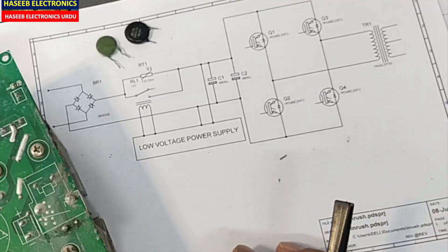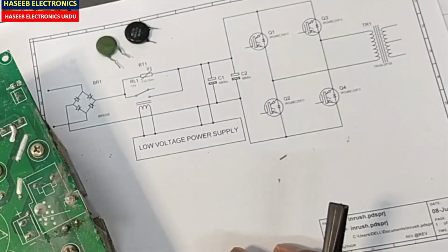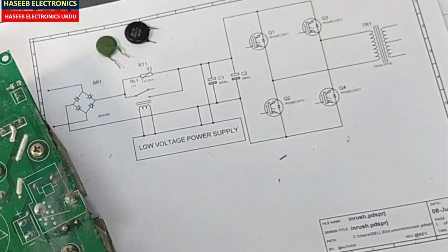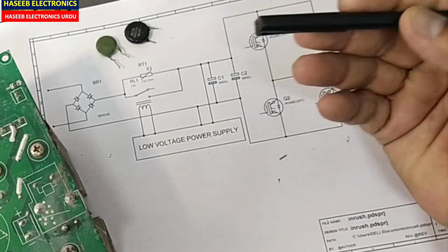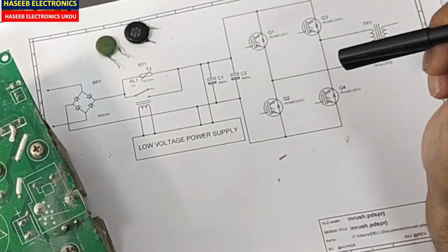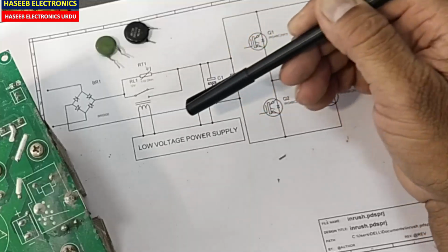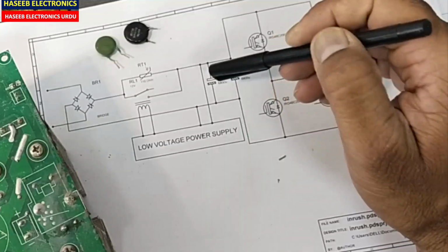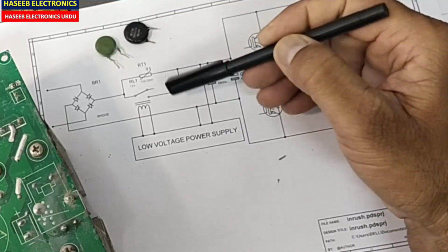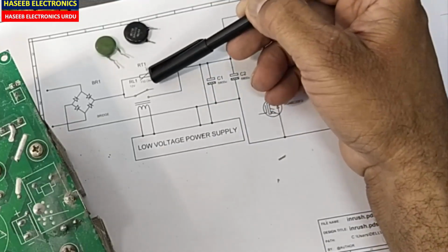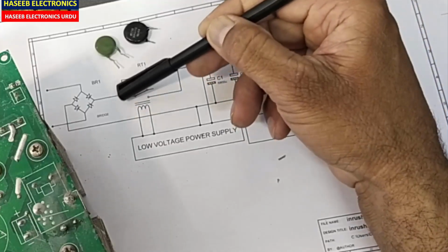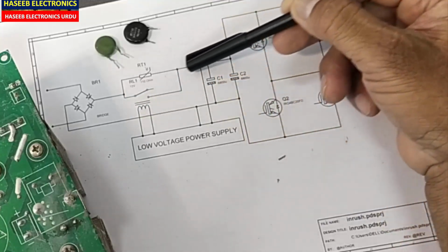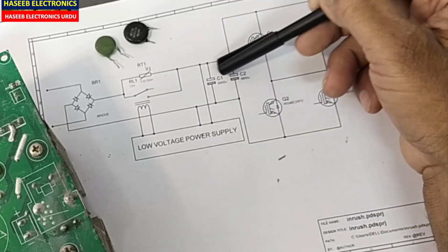To protect it from a huge short circuit current, the inrush current, which is most of the time approximately 10 to 20 times the system current, since it will damage the machine. To protect it from any damage and from overcurrent losses, a PTC or NTC is used in the positive series line. So current has to pass through it to charge these capacitors.